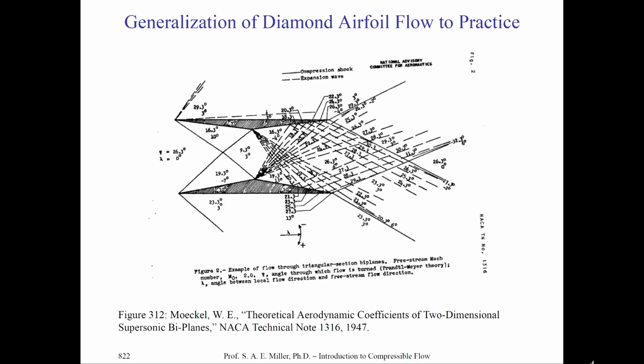Here's another particular angle of attack and positions of the plates. In this case, we have the same fronts. Of course, this is the full analysis. And through, of course, our Prandtl-Meyer theory, you can see indeed, if we march downstream from cell to cell where the expansions cross, we can calculate every angle of degrees of each of the waves and, of course, marching downstream, their new properties simply by looking up each particular Prandtl-Meyer expansion function and corresponding flow turning angle from states like, marching downstream from one state to another. And that's how, of course, these types of problems are done in practice.